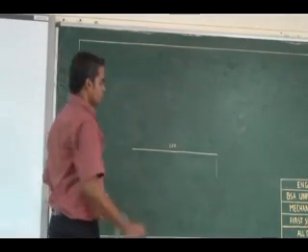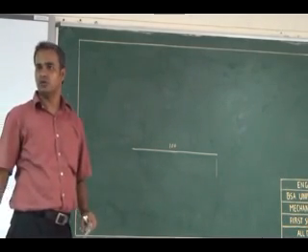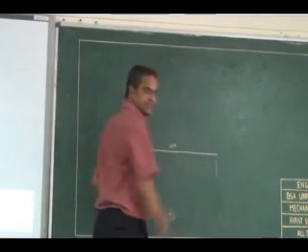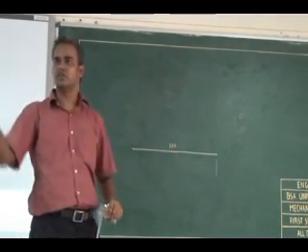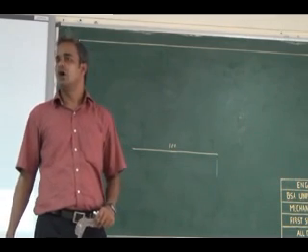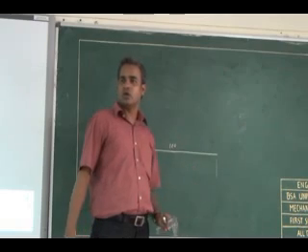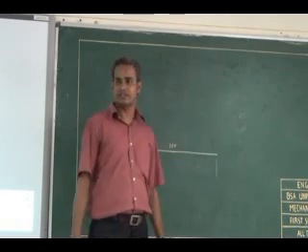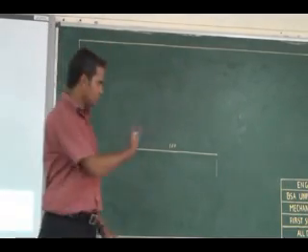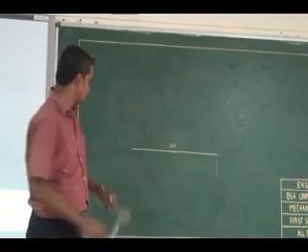This gap should be a minimum of 2 mm, because the extension line should not touch the entity. Otherwise it will look like an edge, an object line. So you should leave a 2 mm gap, then draw the extension line. What pencil do you have to use for the extension line? 2H. It is a thin line, a 2H line.